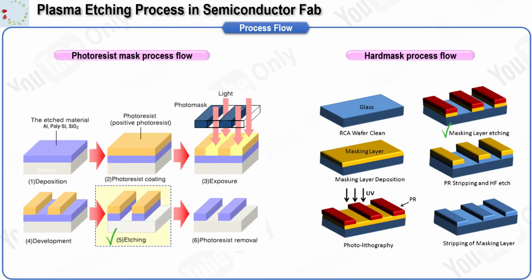Hard mask deposition uses plasma-enhanced chemical vapor deposition, low-pressure chemical vapor deposition, physical vapor deposition, or atomic layer deposition depending on stress, conformality, and thickness targets. Thickness is set by the selectivity budget and the overetch margin. A typical hard mask is 1/3 to 1/2 of the resist thickness that would otherwise be needed. Thicker hard masks improve durability, yet they also increase etch time during the open step and can add reflectivity issues for lithography, so balance is important.